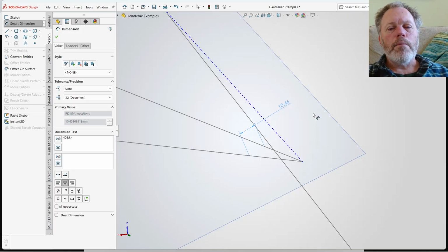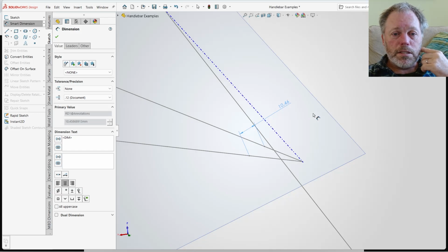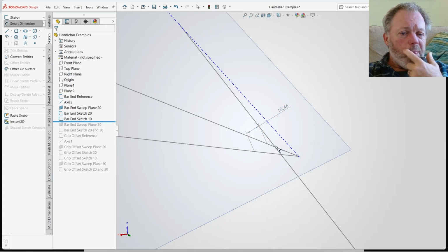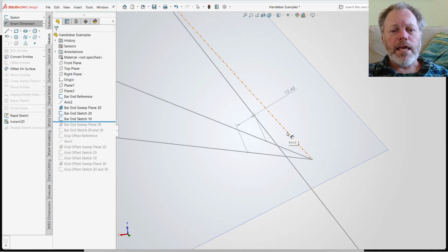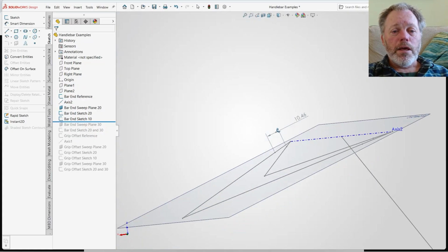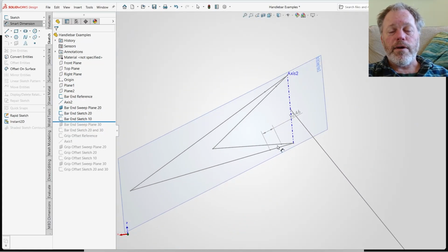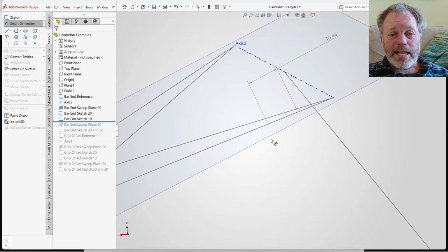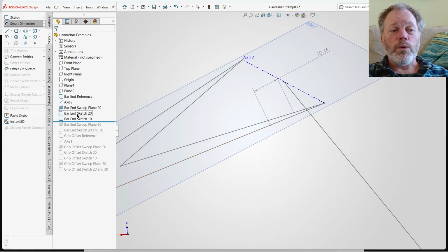Anyway, but you can get some 12s, is that right? 12-degree mountain bike bars from not Syntace, the other company. Anyway, that German company. But the point being here is that if we're taking a distance from this axis, which is the end of the handlebar, we've got a big problem here, okay? Because we didn't intend the effective body reach to change by 10 millimeters, but it did. And that's entirely dependent just on the sweep angle.